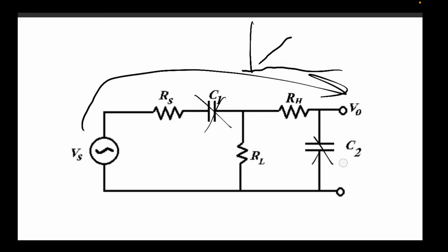If I considered high frequencies, this would be shorted, and this would be shorted. Well, what is V out over a shorted capacitor? Would that also be 0, right? And so you've got this gray area in between where on one side they're both open, and on the other side they're both shorted. In each case, they are going to 0.